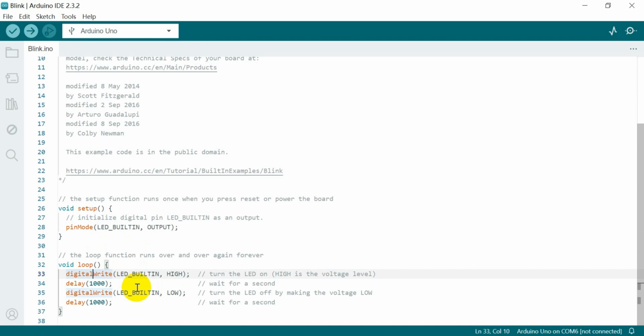I made another lesson on this. I think it will be a few lessons down the road in this course. And it's saying LED_BUILTIN, so pin 13, and turn on the voltage level to HIGH. So this means it is giving power now to the LED L, and we can now turn the LED on.